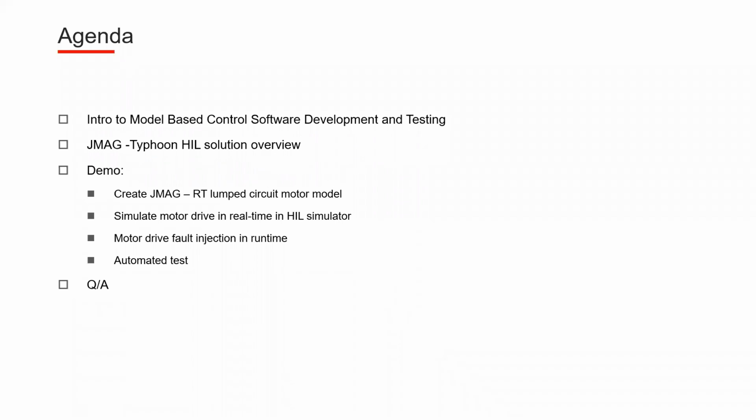We'll show how to build a power stage in Typhoon, how to import the JMAG-RT generated machine model. We'll run a simulation, do a couple of scenarios like fault injection and some torque steps, and we'll show an example of an automated test. And we'll leave some time at the end for the Q&A.